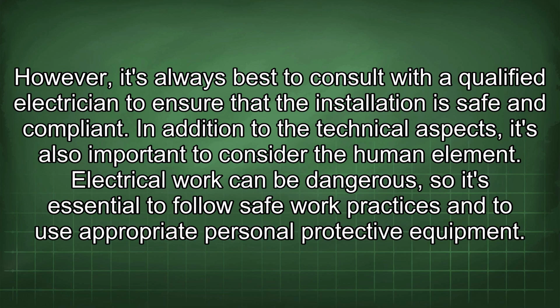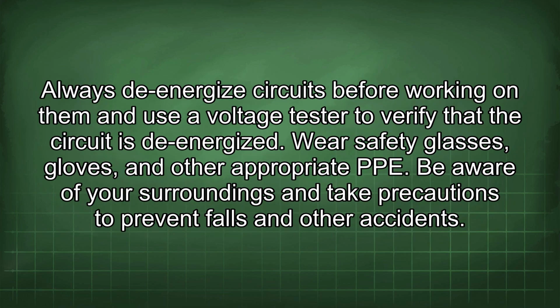In addition to the technical aspects, it's also important to consider the human element. Electrical work can be dangerous, so it's essential to follow safe work practices and to use appropriate personal protective equipment. Always de-energize circuits before working on them and use a voltage tester to verify that the circuit is de-energized. Wear safety glasses, gloves, and other appropriate PPE.